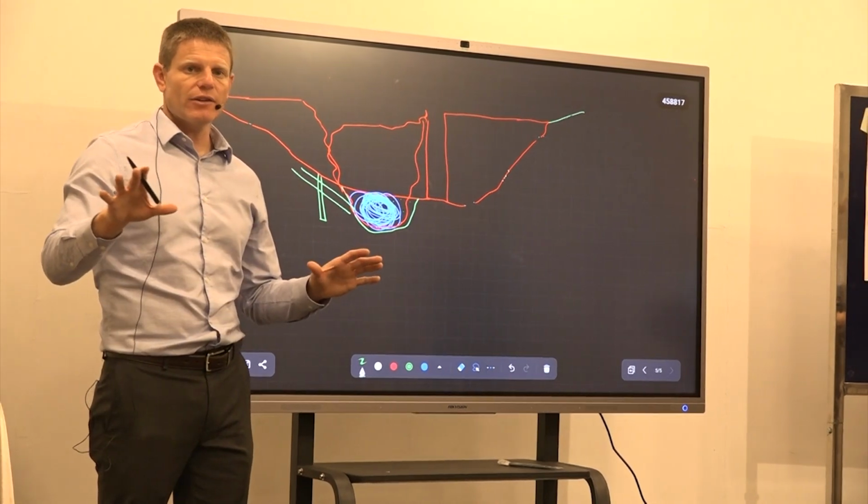Is there anything else? Any other comments? Yeah. Design phase, we can apply remedies for this kind of failure, because during the design of concrete, we also deal with the shear force. And the shear reinforcement within the concrete structures is there to resist those sorts of forces. So this is not likely to happen. I think so. That's right, yeah.